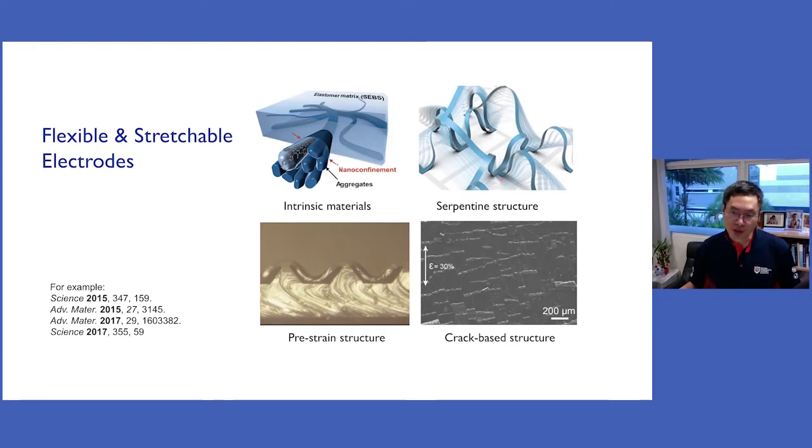The second typical example comes from John Rogers from Northwestern. His group developed silicon-based devices, but uses mechanical design to make the structure bendable and foldable in three dimensions. When you stretch it, it doesn't change the electrical properties of the silicon electrodes. The good point is they can align with current CMOS technology, but the problem is a lot of additional methods or modification approaches are needed.